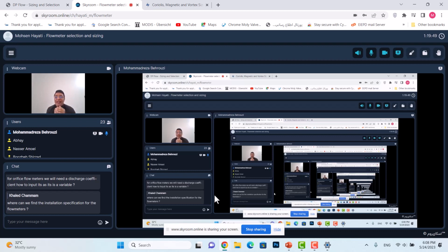And I told them, look, if you look at the content from the start to the last page of the documents, you can understand that this TD or PD means sizing temperature, sizing pressure, not mechanical design pressure or mechanical design temperature at which the pipe is going to explode. So first mistake. Second mistake,